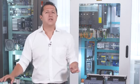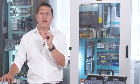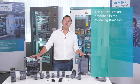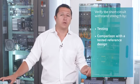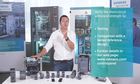All of these standards tell you how the short-circuit capacity or the overall short-circuit rating of a control panel must be determined. According to IEC 60204, this can be done by tests, by application of design rules, or by calculation. The procedure can be based on the standard IEC 61439-1 or on other IEC technical reports. The most common procedure actually is according to 61439-1. The following methods can be used to verify the short-circuit withstand strength: either verification by testing or verification by comparison with a tested reference design.